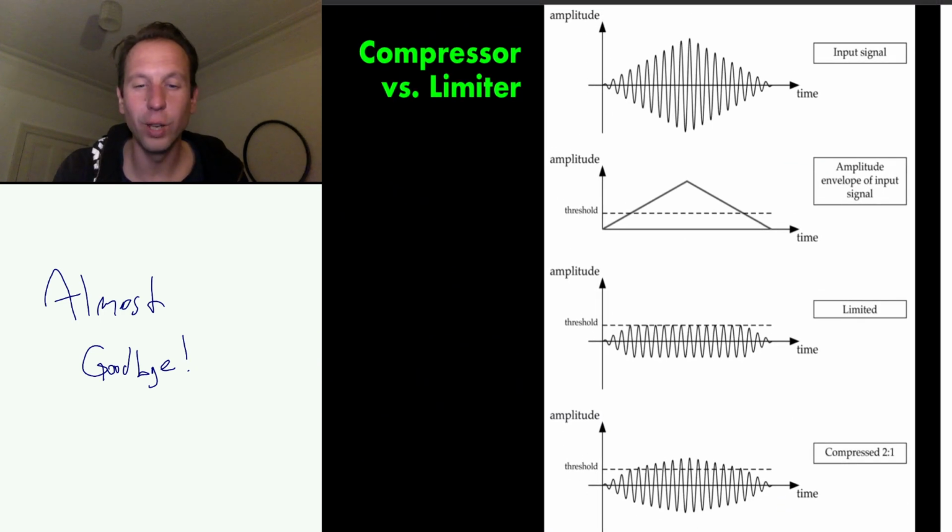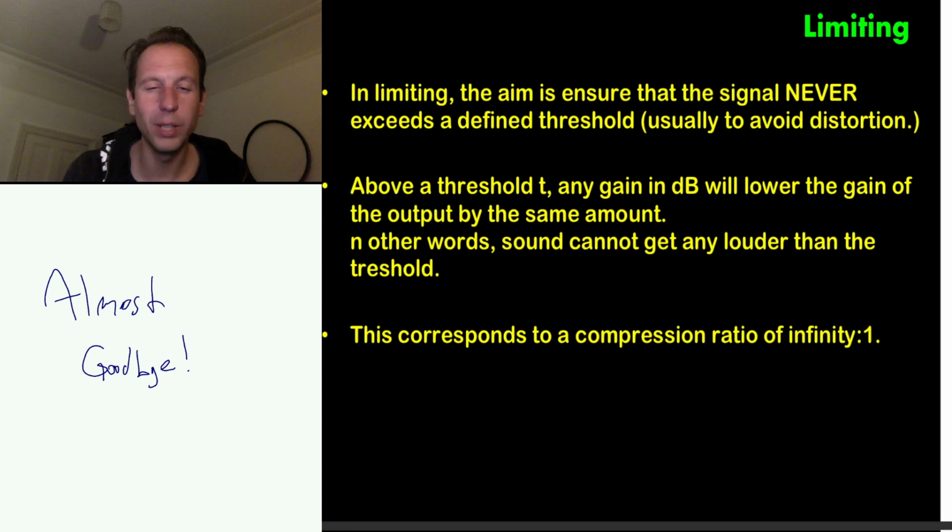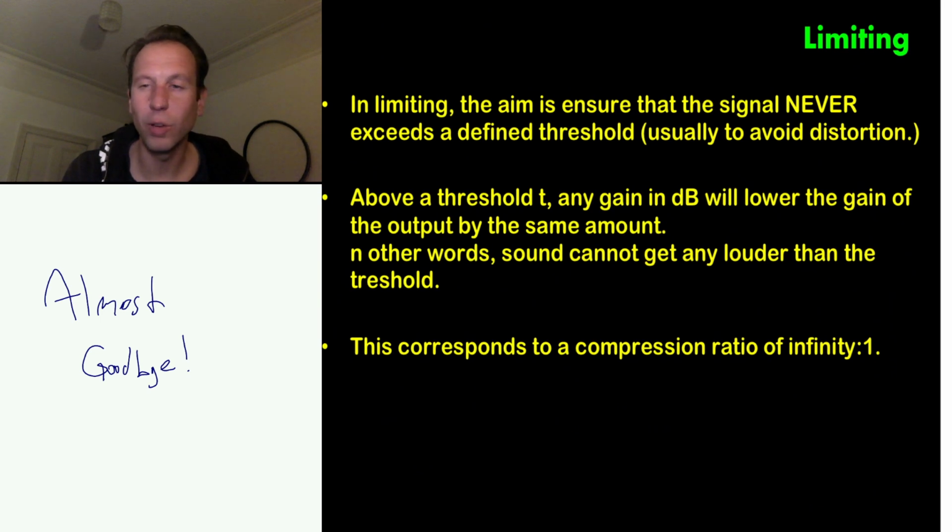Briefly, in comparison to the limiter, what you see here is that the limiter, which is the third graph, is actually limiting the signal, whereas the compressor typically allows it to come through a bit more. That has to do with the ratio, meaning that above threshold some signal can come through as well. And then also, depending on attack and release parameters, the attacks may come through a bit louder. So all these settings can make quite a difference. A few more bits about limiting. As said, it will actually make sure that it never crosses the limit.